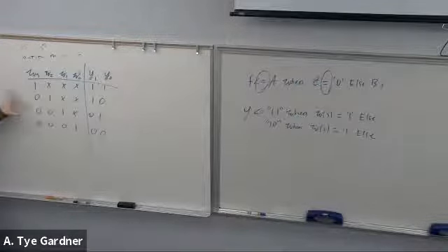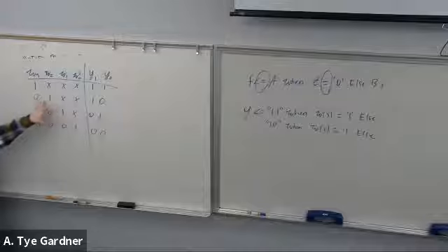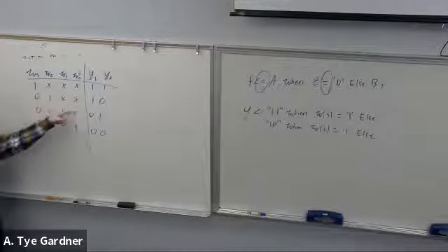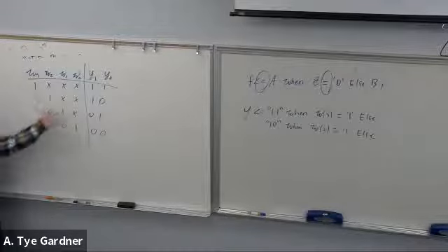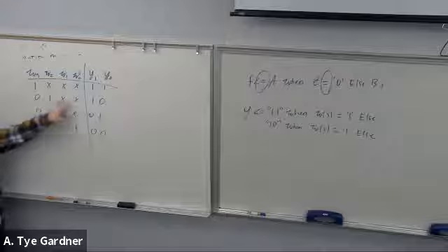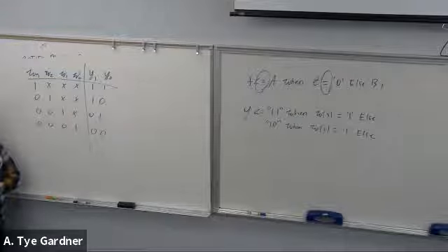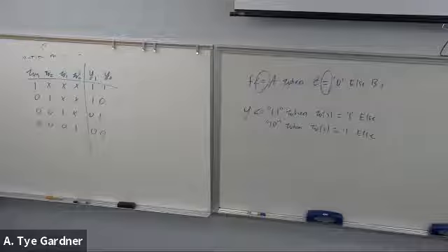So something is passing these inputs, and if those outputs could have all these don't cares in them, it's very happy because don't cares in a K-map mean it's easier to simplify, right? So that's what the priority encoder does for us over a regular encoder, because it just doesn't care what's happening in this. Whereas a regular encoder would need zeros at those locations. So it simplifies the upstream logic a whole bunch for us.